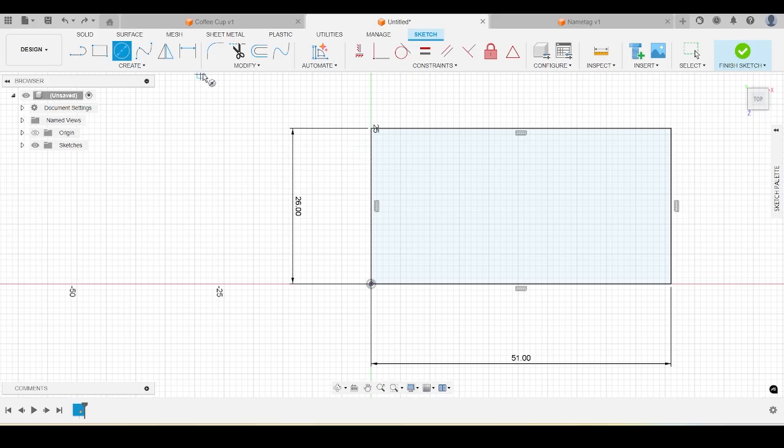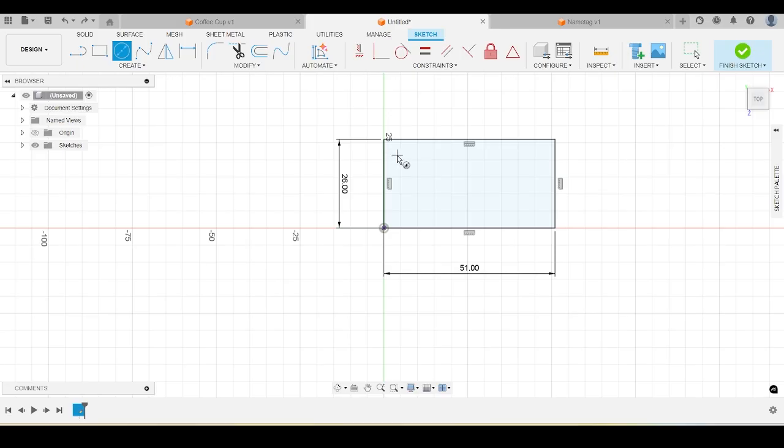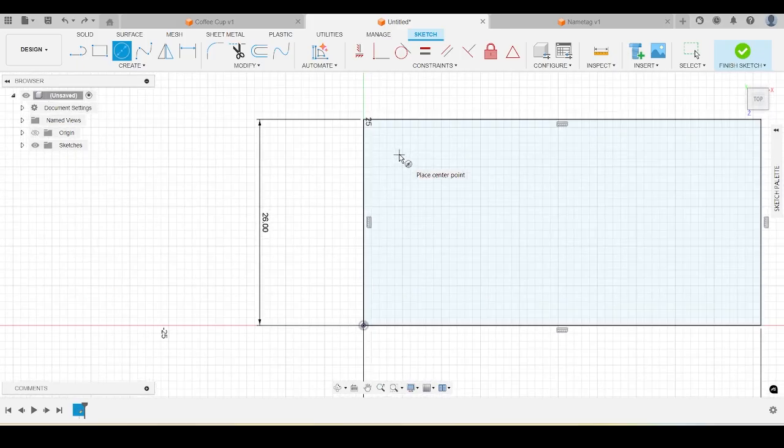So when I click on this circle, you'll see I'll get a little target, all right? And that nicely clicks anywhere that the grid is. So that's why I quickly zoomed in just a second ago, so that I can snap onto my millimeter by millimeter grids. Because if I zoom back out again, it doesn't snap anymore, and it's a little bit fiddly. So I'm zooming in so I can see my millimeters. I'm going to go 1, 2, 3, 4, 5 millimeters across, and 1, 2, 3, 4, 5 millimeters down.